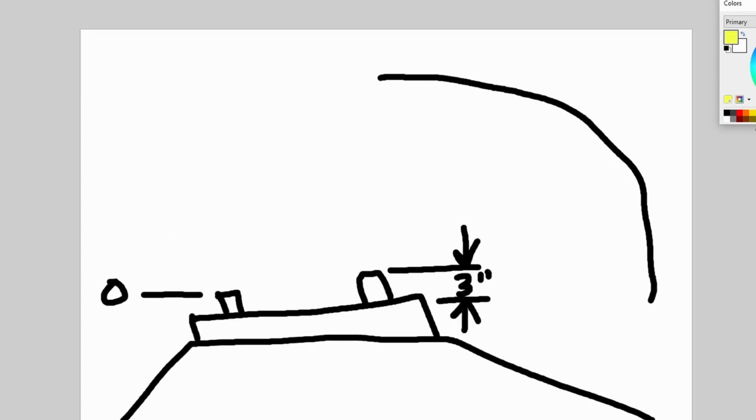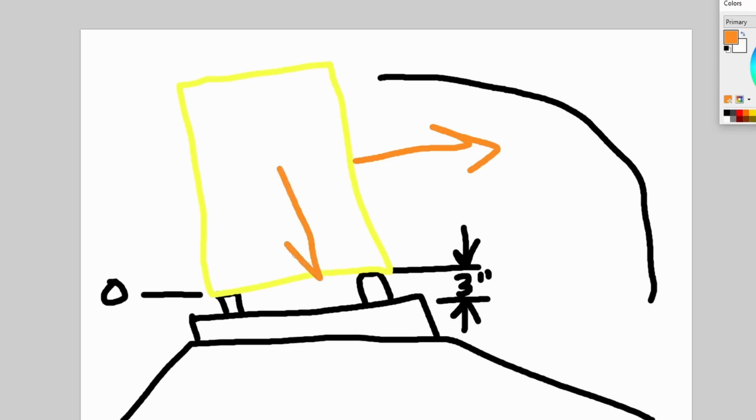And what does that get us? Well, that means that when we put a train on it, the whole train will kind of lean that way. And as the train is going around this sharp curve, physics is saying, I want to throw this train off and make it tip that way. But now we've countered physics by saying, rather than the weight going down towards the center of the train car as we normally have, now the weight is slightly counteracting that we want to fling you on the outside. It's the same reason a lot of racetracks have banked corners. We can have a banked railroad turn.